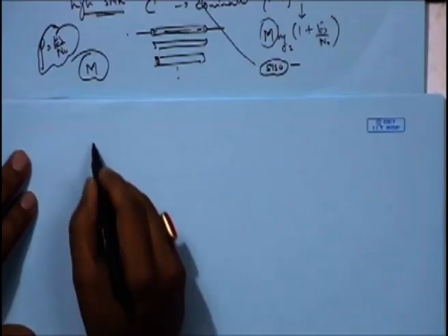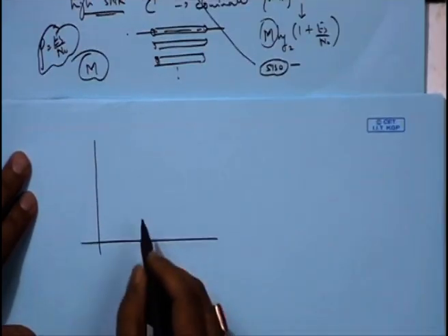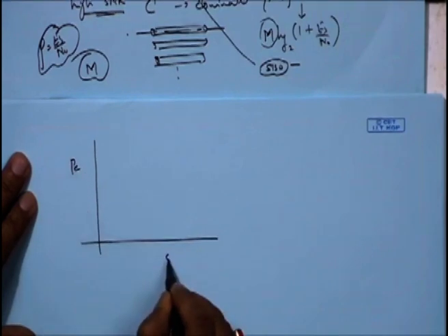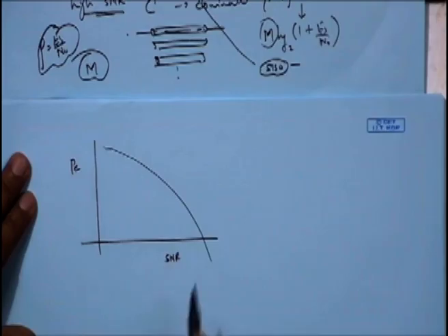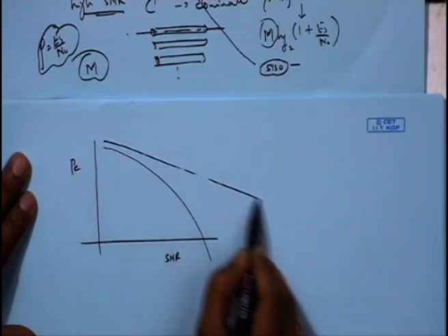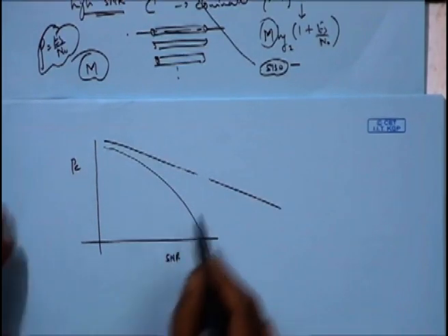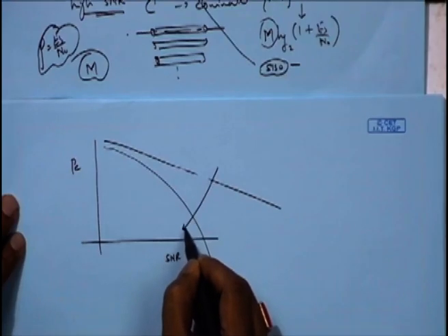When you are using modulations, we always know that the relationship of probability of error with SNR for an AWGN channel is like a waterfall, whereas for a Rayleigh channel it is almost like a straight line, and as you increase your diversity order it becomes better.